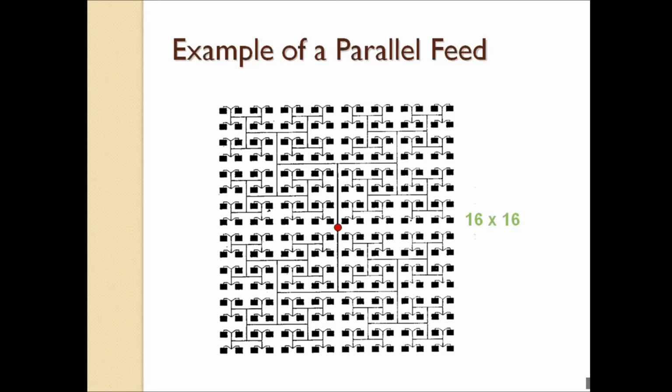When the antenna is a two-dimensional array, it concentrates the power only in a particular direction. A single antenna has a broad radiation pattern, right? With an array of antennas, the radiation pattern is sharper, right? When the radiation pattern is sharper, you can track the signal to any point. With a broad radiation pattern, a single antenna will cover a 60-degree half power beamwidth.